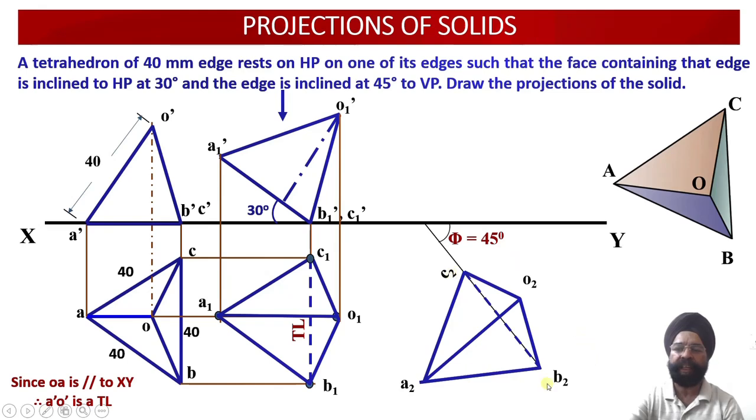So having located all these 4 points over here, now we have to join all these 4 points in the same manner as they were done in the previous plan projection view. That is, whichever lines were dark, they will be drawn dark over there, and whichever lines were hidden ones, that is dotted ones, the same line we have drawn over here as dotted one. So this is the top view of an oblique lamina which is inclined with both the reference planes.